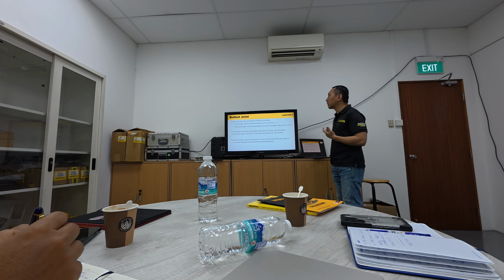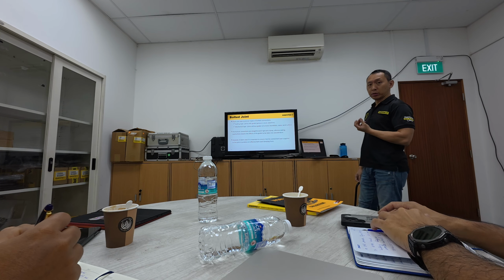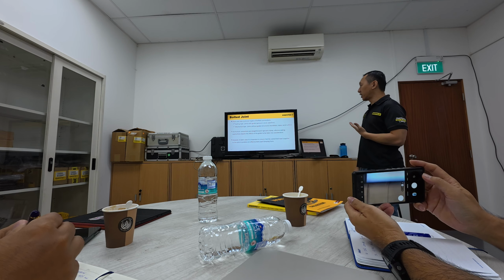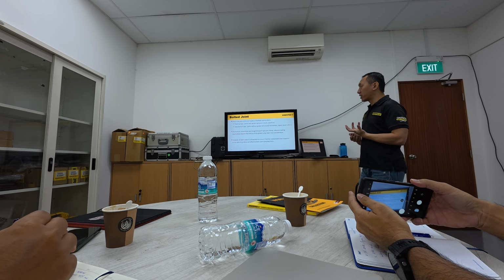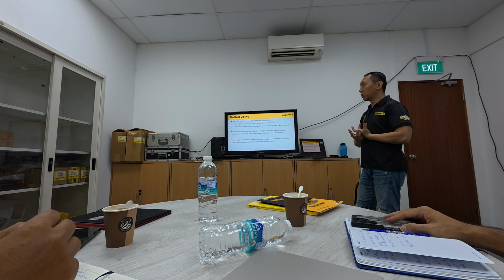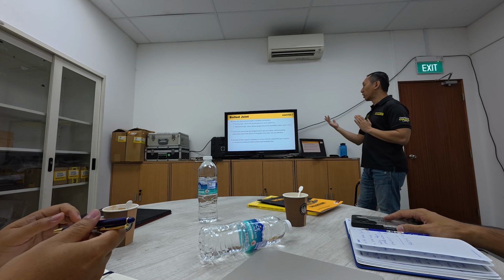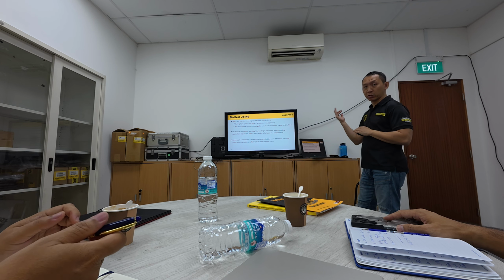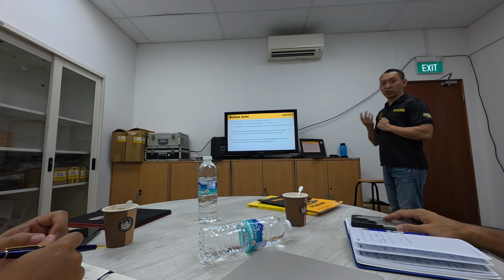So there are two common types of bolted joint. The seal type, that means the joint with a gasket, where there will be pressure in the vessel or pipeline. And the mechanical type, that means a joint without a gasket, with no gasket in between the two joints. That includes structures, foundations, cranes, wind turbines. So these are joints that you might encounter also. There are also structural joints.